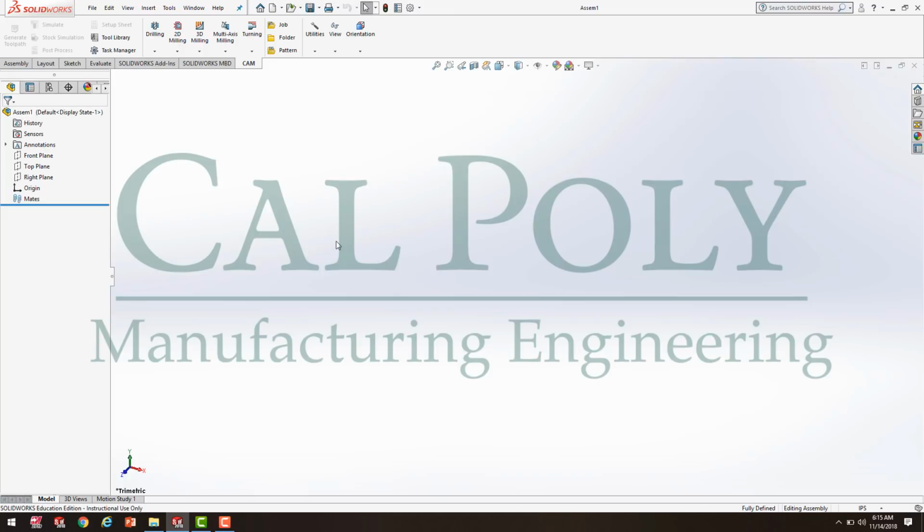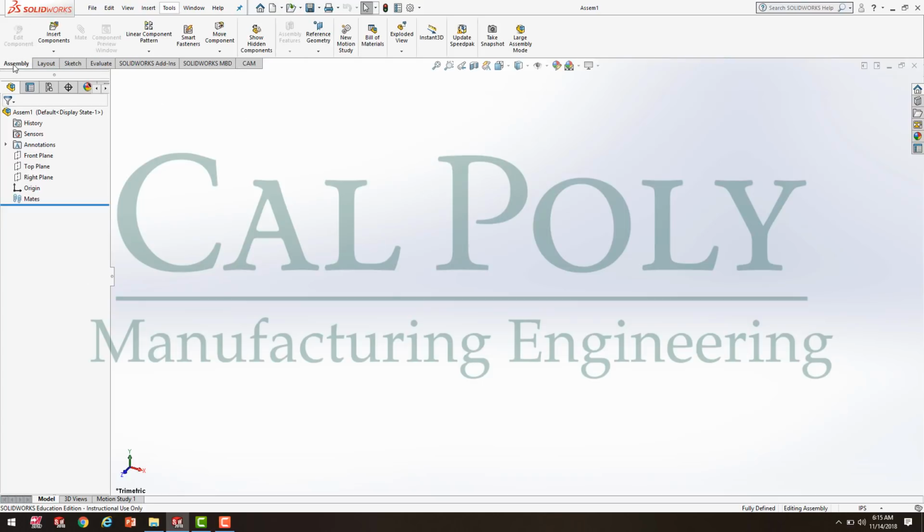At this point, I'm going to hit Cancel, and I'm going to press X on the Begin Assembly. We're going to look at a few things before we start assembling. Remember, the assembly environment has the assembly ribbon bar here, which allows us to insert components, mirror or make patterns with components, move components or rotate them, and then also create an exploded view. So we're going to start assembling parts in this environment and then create an exploded view so we can show it in the 2D drawing environment.